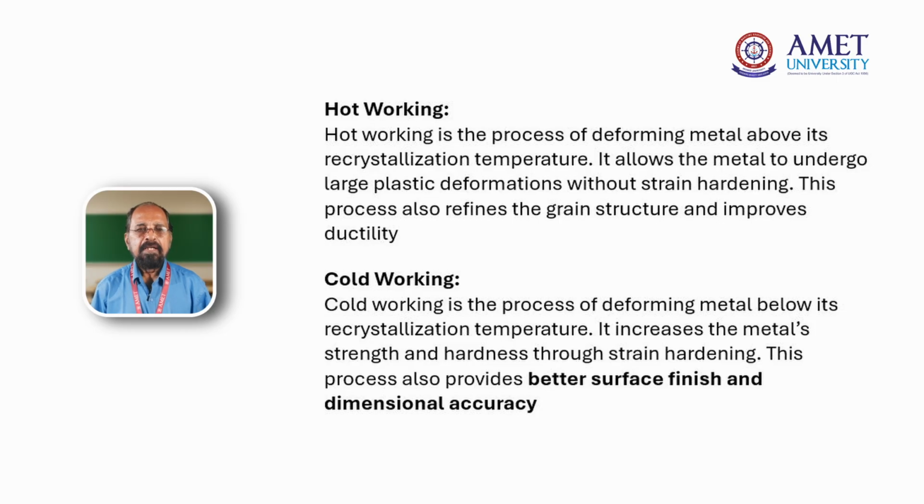Any material heated up to 60 to 75% of the melting point of that metal is converted into different shapes. In cold conditions, the same metal can be converted into different products at room temperature. This is called the cold working process or the cold bulk deformation process. In both the cold process and the hot process, 90 to 95% of the material is converted into the final product without sacrificing the properties required for the particular product.